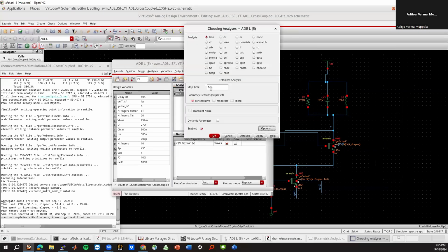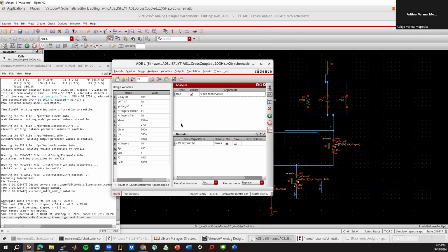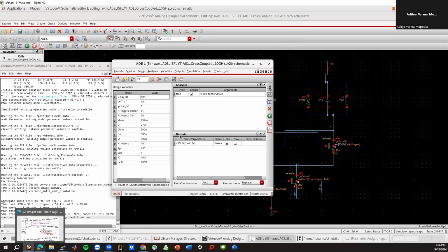So I can change this now to 16 nanoseconds, which makes things a bit faster. And I can change the delay of when to measure. No, that's not where we're measuring. So that's fine. That's when the pulse hits, right? So once the simulation is done, we still need to know what this needs to be, the delta T ISF and what the I pulse value needs to be. But at least we know when to start the delay and then when to collect the impulse response.